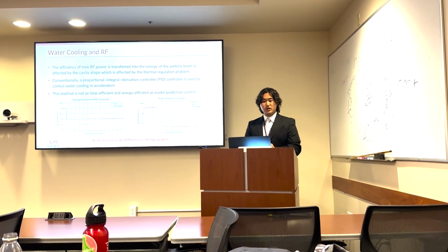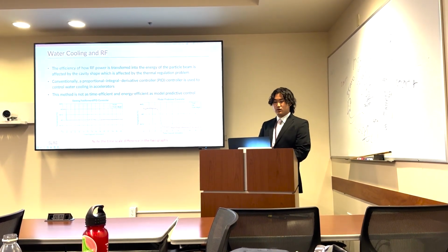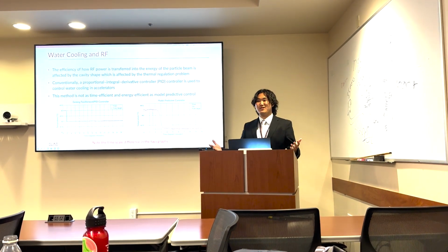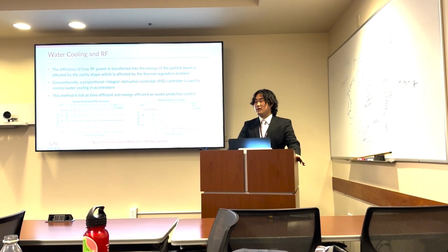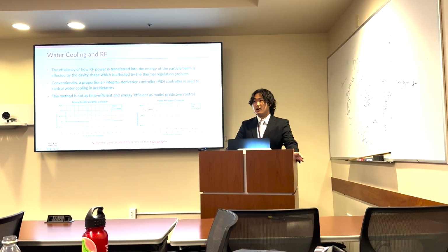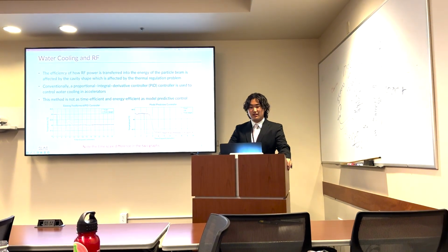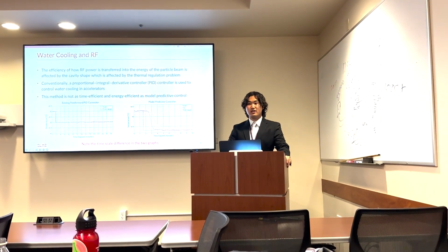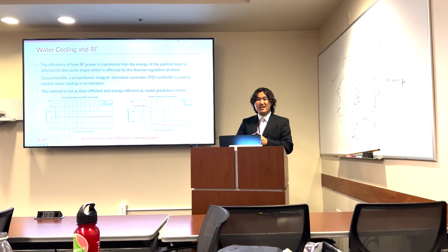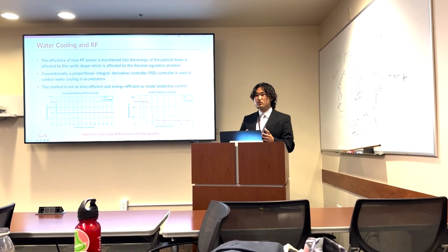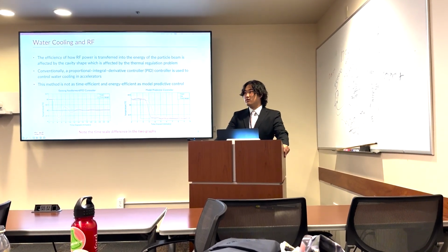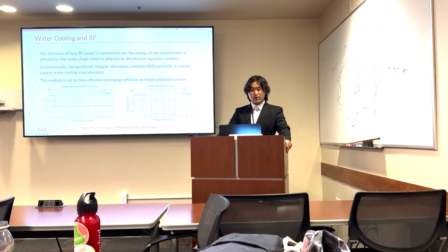So I'm gonna go into a little bit of how the water cooling system works, right? And how that relates to RF, and why do we care in the first place, right? And we care because it turns out that water cooling has a big impact on the radio frequency that's generated, right? And it's literally dependent on a thermal regulation problem where you're getting a copper cavity in the accelerator literally expanding and contracting due to the heat surrounding the cavity. And that in turn, like I said, affects the radio frequency power.